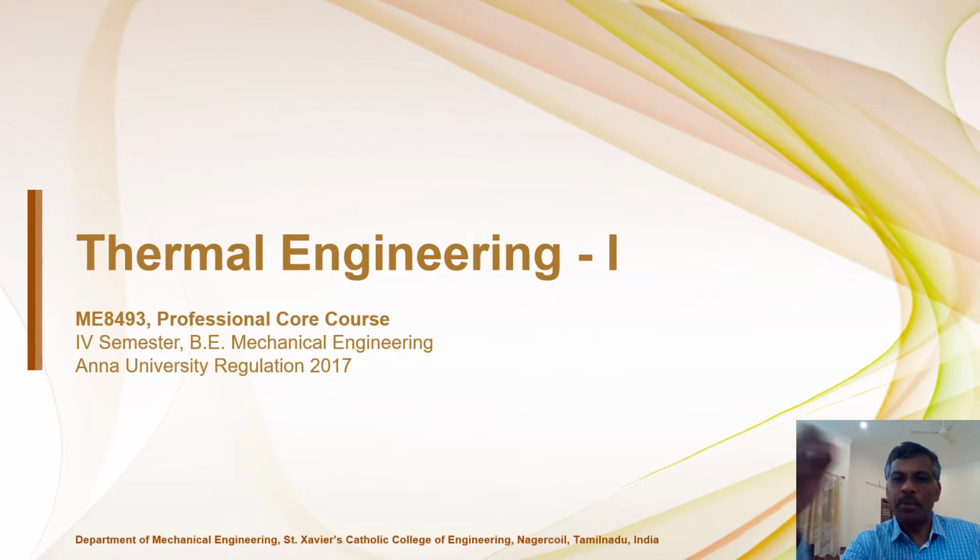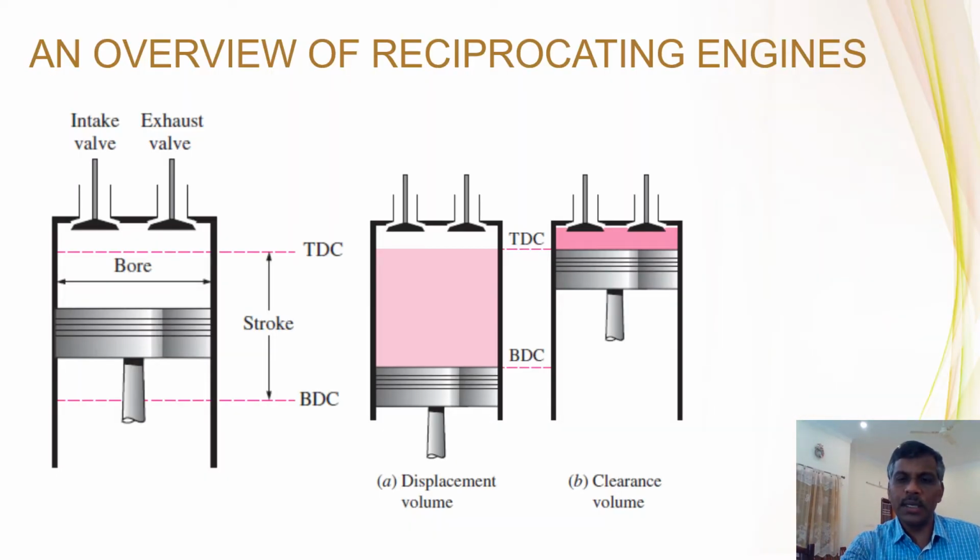So we will do some problems on what we have seen in our standard cycles. Before going to that, I wanted to recollect what we have learned earlier. The nomenclatures of ICE engines, you always keep it in mind. The stroke length, that is the length of stroke, and the diameter of the piston. These two things you keep in mind so that we can calculate the swept volume.